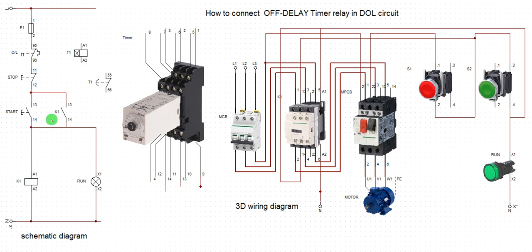Let's start from the schematic. If you want to incorporate this timer into this place of delay timer, what we're going to do is to cut off the supply to the contactor coil, take it off here. All right. Then put the contact here. So it will pass through contact NC before coming here. On this one shutting off, it will now shut down the system. Then you also place the coil of the on delay timer, off delay timer rather.